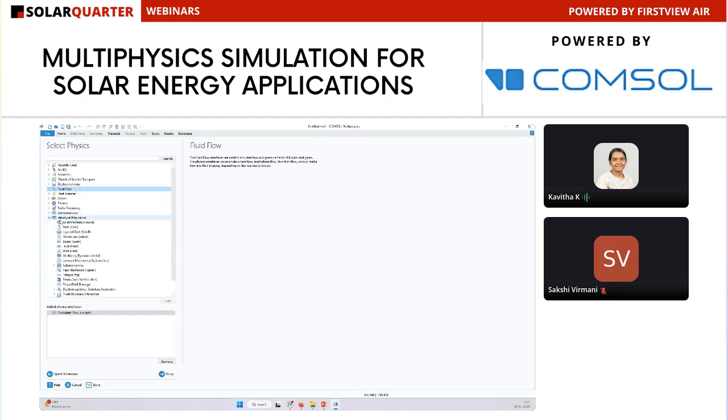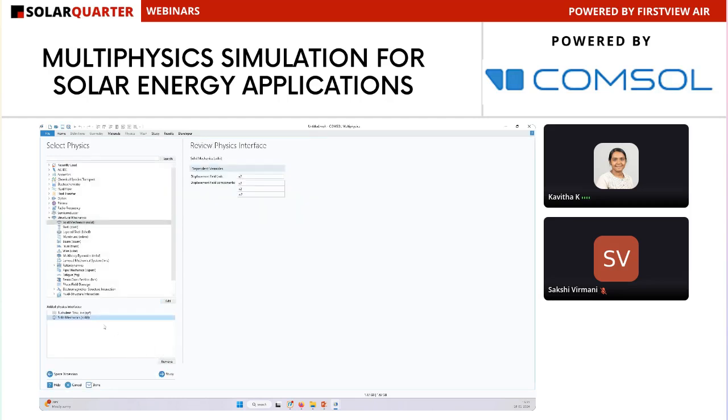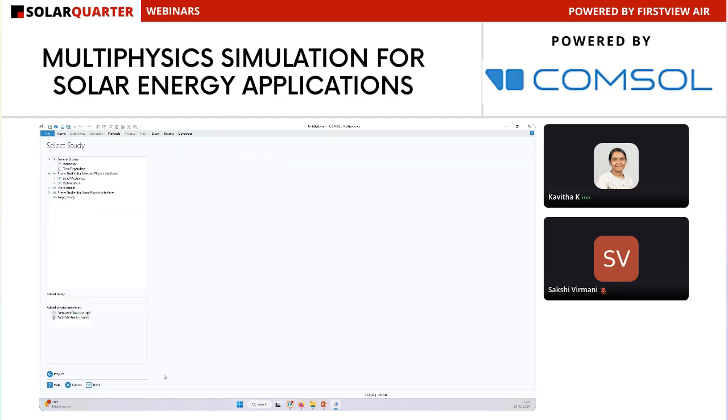So we will choose the structural mechanics, solid mechanics interface. I'll click add. So now two physics interfaces are added since I'm going to solve these two physics. If you want to add more, then you can keep adding as many physics as required for your application. Then you can click study.